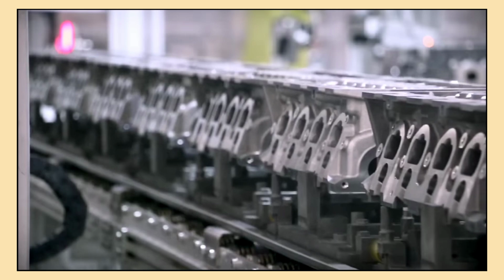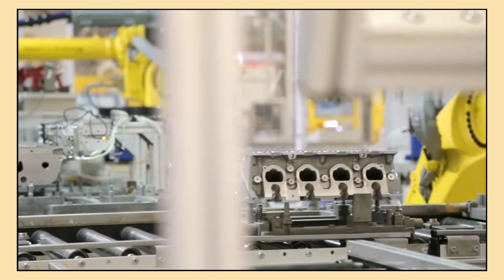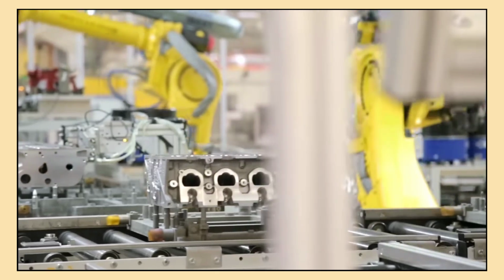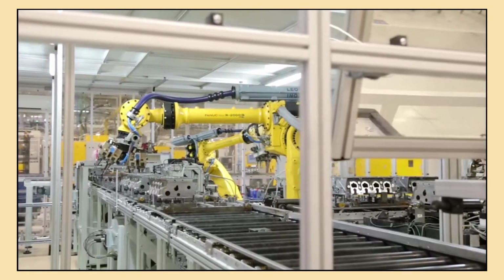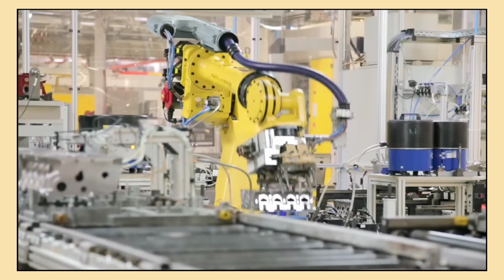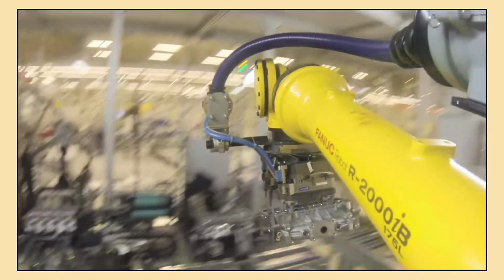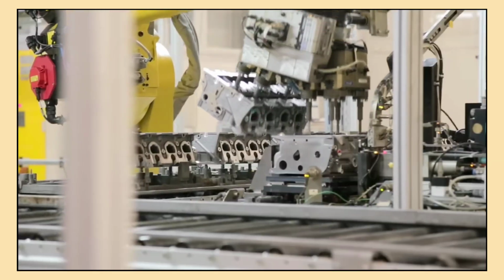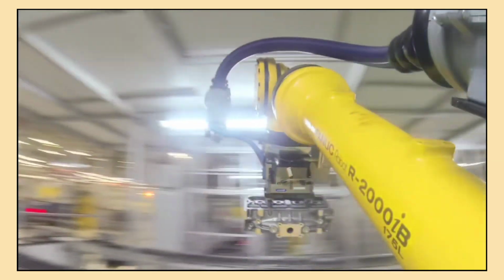Let's look at a real-world example. Imagine a production line with a conveyor belt. The PLC is responsible for controlling the movement of the belt, checking for any items on it, and triggering other machines to perform actions like packaging or labeling. Here, the PLC receives input from sensors on the conveyor belt to detect when an item arrives. Based on the data, it sends an output signal to start or stop the belt or to trigger a robotic arm to pick up the item.